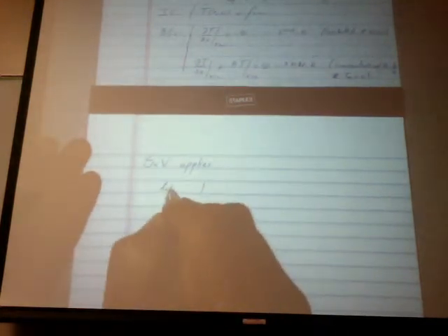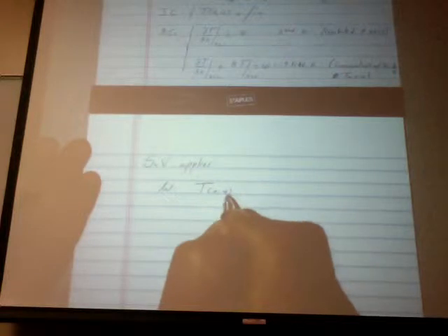Alright, so how do we deal with this problem? Since all the conditions apply, the governing equation is homogeneous, the boundary conditions are homogeneous, and the initial condition is non-homogeneous, and we obviously have a linear separable problem, SOV applies directly. That means that we're going to let T of x and t equal to some function of space x times some function of time tau. Same thing we did with x and y, now we're going to do with x and t.